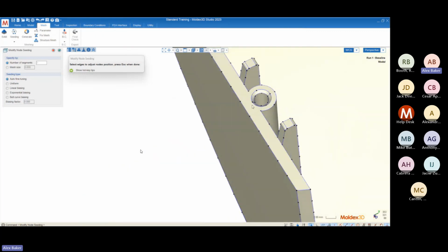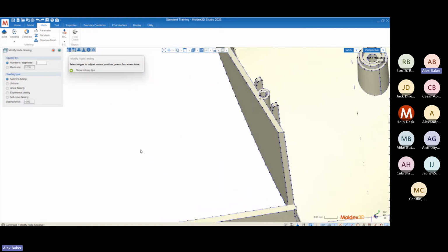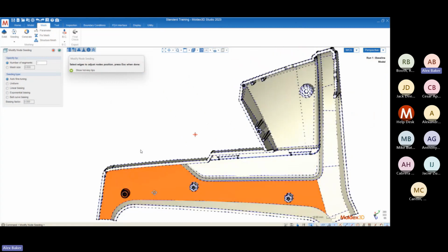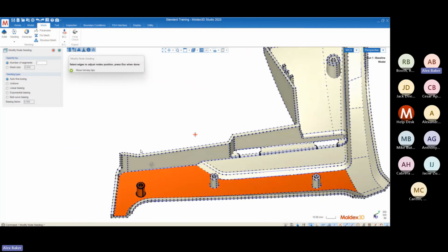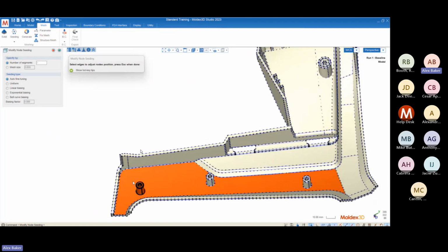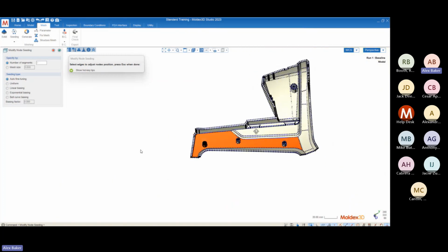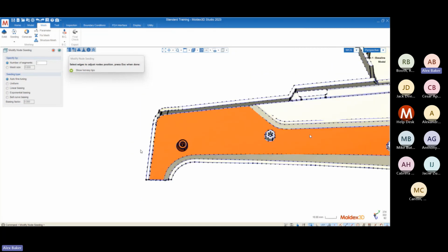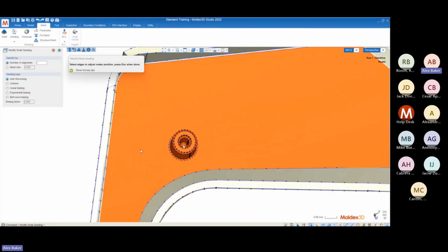Kind of like what I mentioned with the tiny edge, like this guy over here, we want to avoid a large amount of surface mesh size variance specifically. So I don't want to go in and refine every single small feature on my part. I usually only want to refine the ones that are crucial to the analysis. So for example, if I'm not even too interested in these bosses for the analysis, I might not spend the time for the elements to go in and refine them.